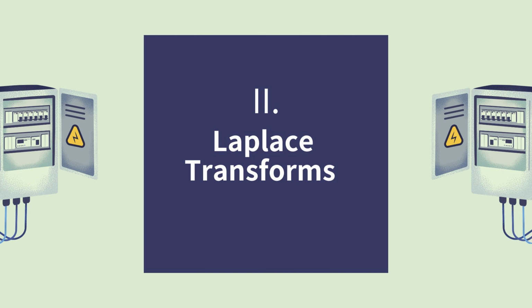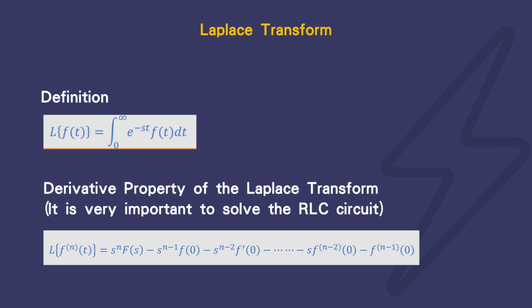Second chapter is Laplace transform, which is useful for solving RLC circuits. We look at its definition first. The Laplace transform of f of t equals the integral from 0 to infinity of e to the power of negative st times f of t with respect to t.